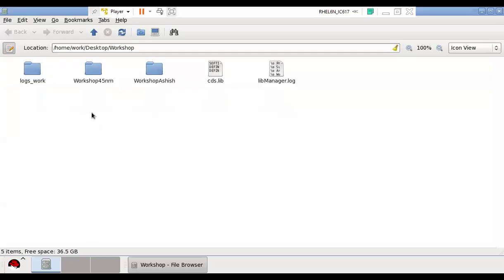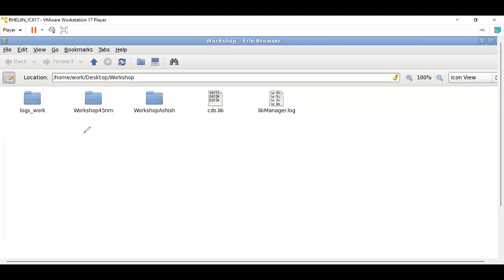So as I told you, there are two different things. One is process corner analysis, one is Monte Carlo analysis, and we would be doing both. Process corner analysis means that you will be using NMOS and PMOS in different ways.